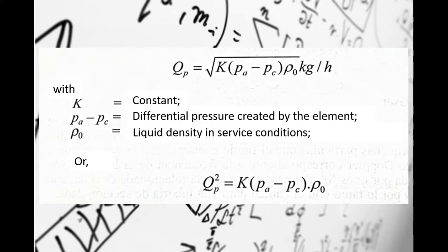The differential pressure signal PA minus PC captured by the corresponding transmitter must be multiplied by the signal from the density transmitter, which is carried out in the compensator. The measuring range of the density transmitter is set so that the correction factor is 1 when the transmitted density corresponds to that of the calculation. If the density transmitter is in a standard condition, the output signal must be manually or automatically corrected for temperature variations in the line prior to input to the processor.